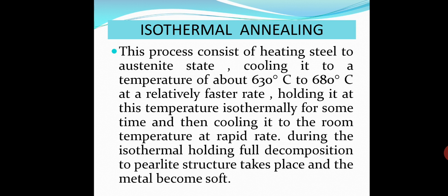So in isothermal annealing, it is cooled at a relatively faster rate, then kept isothermally for a certain time, then cooled to room temperature at a rapid rate.